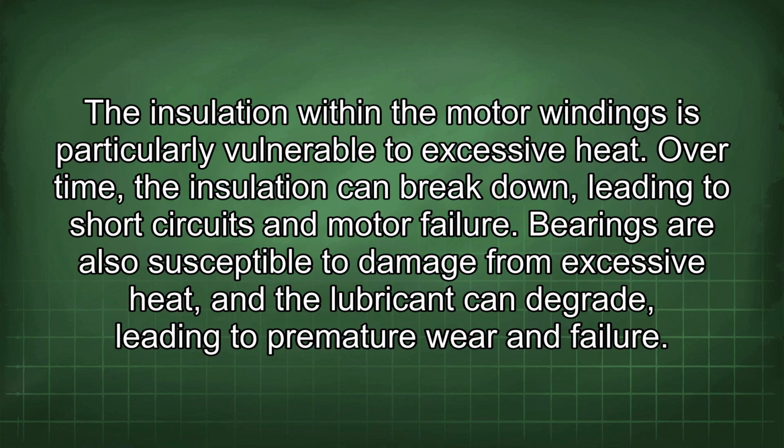The insulation within the motor windings is particularly vulnerable to excessive heat. Over time, the insulation can break down, leading to short circuits and motor failure. Bearings are also susceptible to damage from excessive heat, and the lubricant can degrade, leading to premature wear and failure.